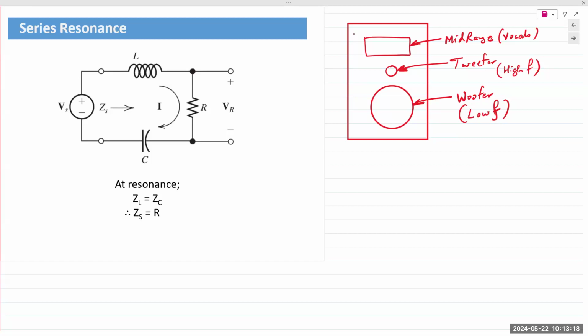There's also a specialized speaker that is typically a separate component, known as a subwoofer, because the lower you go in frequencies, the more power you need to reproduce. You have to actually move the speaker cones physically to recreate the sound waves. Subwoofers reproduce even lower frequencies, basically frequencies lower than 200 hertz. And you need massive subwoofers, like 15-inch or 18-inch speakers, and a lot of power to actually reproduce those. So there's a purpose to this.